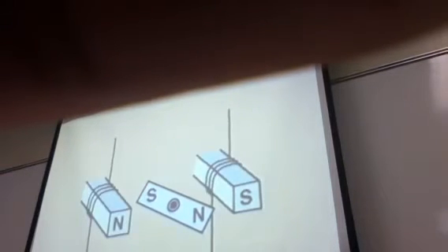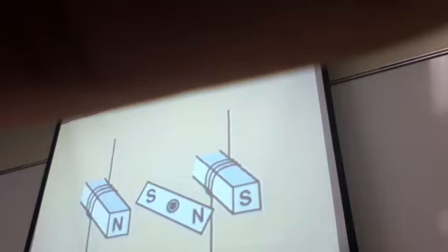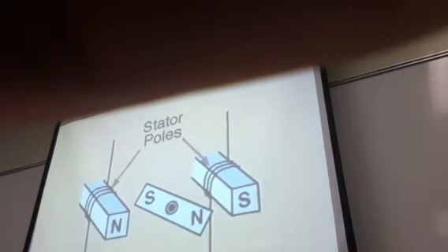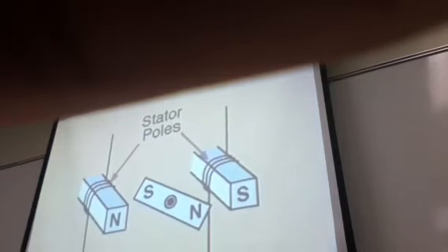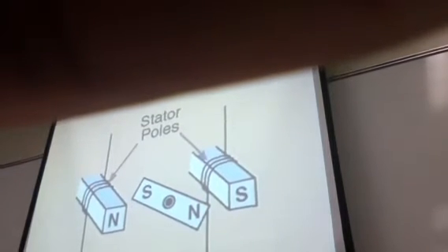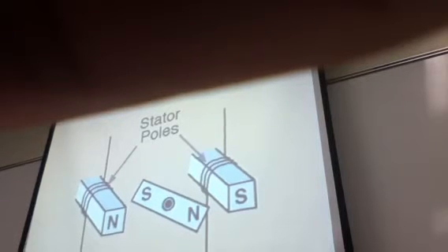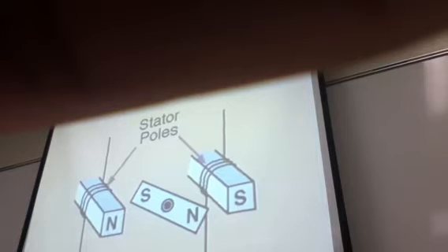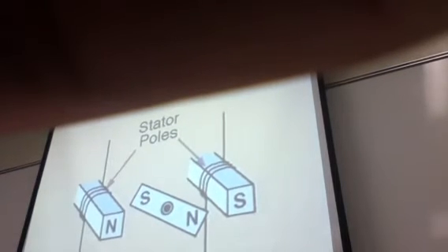Here, the motor is represented by a permanent magnet rotor pivoting on a shaft. The two stator poles have wire coiled around them. Like the coils of relays and contactors, the stator coils produce strong magnetic fields when current flows through them. You will recall that like poles repel and unlike poles attract.